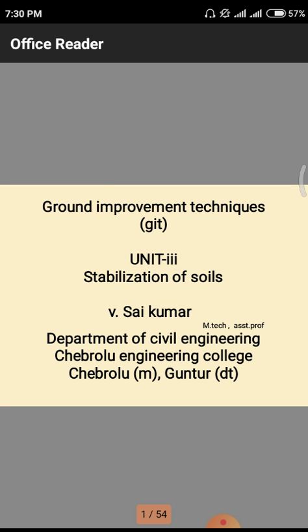And in situ tests, we are having different 4 to 5 tests conducted. Those are done using different equipment, advanced equipment we have to use to conduct those in situ tests. But in case of laboratory tests, majorly we need the vane shear test and triaxial compressive tests. Those two test values are required whenever we are going to construct a project.